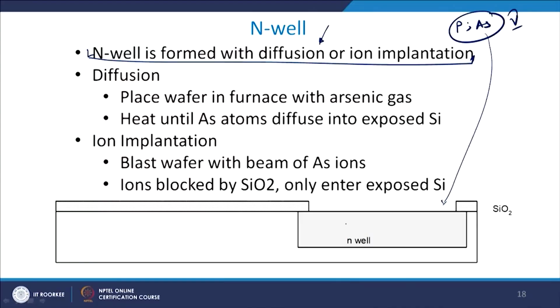So, there is a temperature gradient, and there is also a dopant gradient, which results in the atoms of phosphorus and arsenic coming towards and sitting at these positions, and you do have diffusion. You can control the speed of the diffusion by changing the temperature, and also by changing the dopant species. You can also change the amount of dopant by increasing or decreasing the dose in the ion implantation machine.